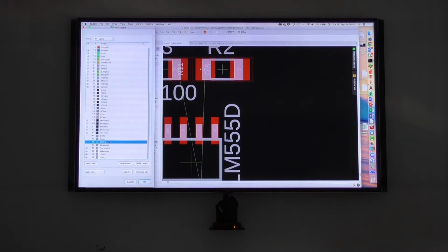You would want to mill the external perimeter and then an internal aperture. I think that's something the board manufacturer has to decide in this process, what to do first. Usually they know what's inside the board should be milled first. Of course, the board contour.